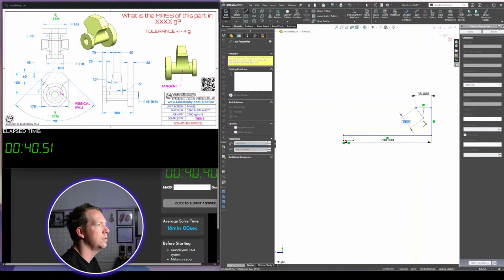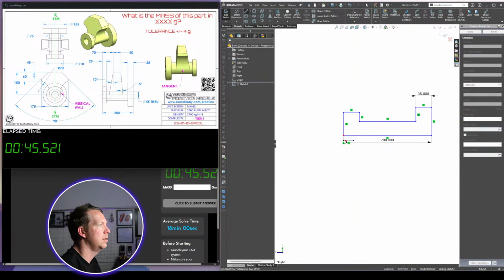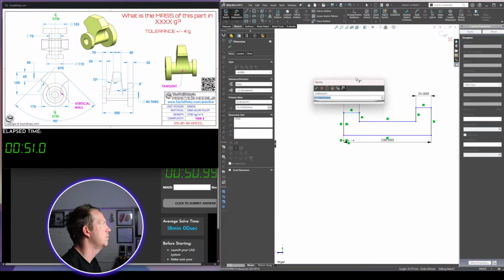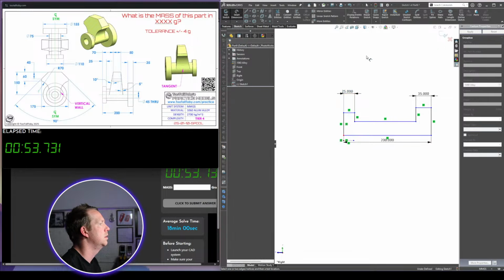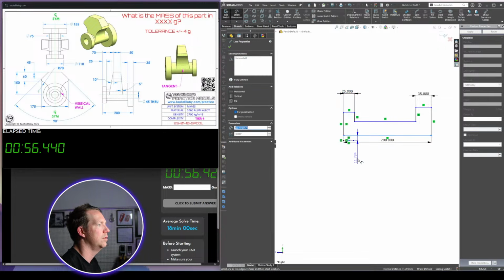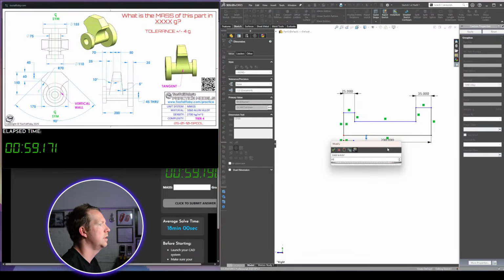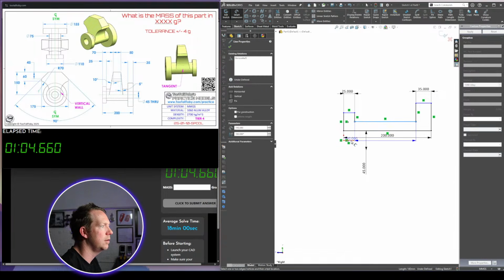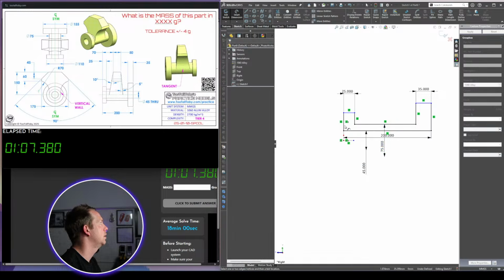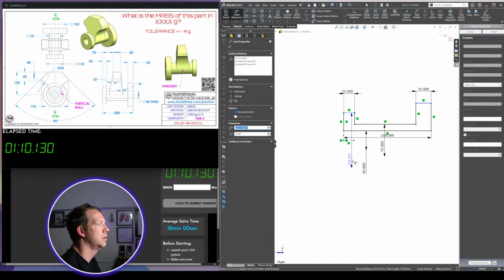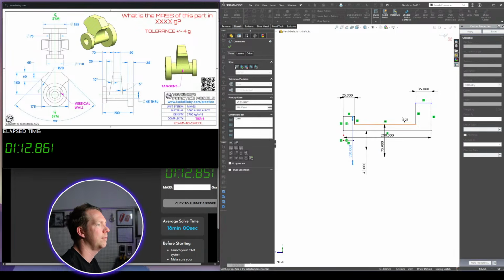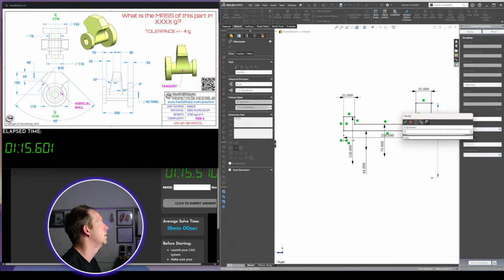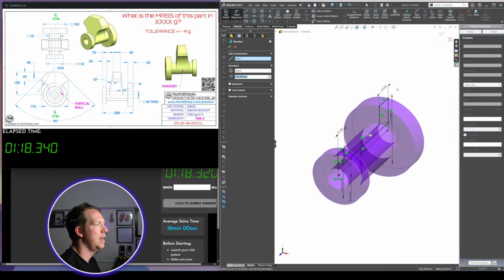It's 35 across, down, through, up, across, down. The front one is 25. We said the hole in the middle was 45 through all. And the main section is 75. At the front we have 110, and at the rear 155. So we revolve that,